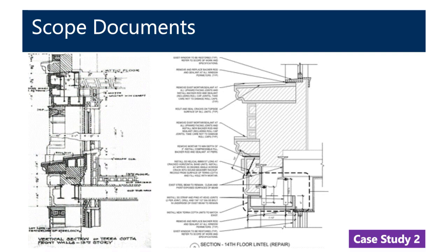We're thinking about the detailing from the standpoint of how this unit can be installed in a situation where it's selective replacement, meaning that the building's not being built from the ground up like it was historically or in the original documents. So understanding how units and how the masonry is supported and how that needs to be addressed in terms of the repairs.